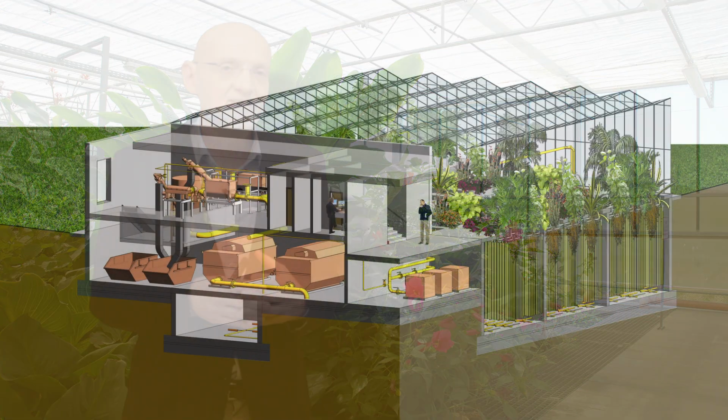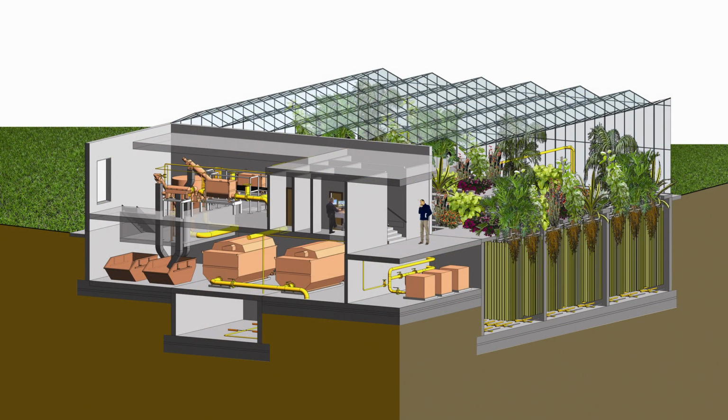The treatment plants, the Organica plants, are designed as a very compact structure. As you can see on the right-hand side of the slide, this is where we have the reactors, the fine bubble aeration panels at the bottom of the reactors. You can see the biomodules, the plant roots in between, the plant tracks, the plants above that, and the enclosing greenhouse.